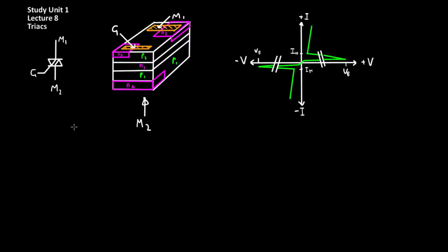A triac is essentially a device which, dependent on the polarity of the pulse applied to the gate, will change the current, or rather the direction in which current conducts. The triac construction is rather complex, so in the example here, which is a triac from only one view, there are several doping regions which will, depending on the input current at the gate and the states of the voltages at M1 and M2, cause the device to behave in different ways.